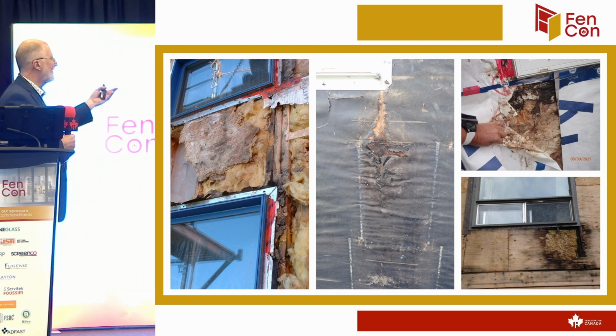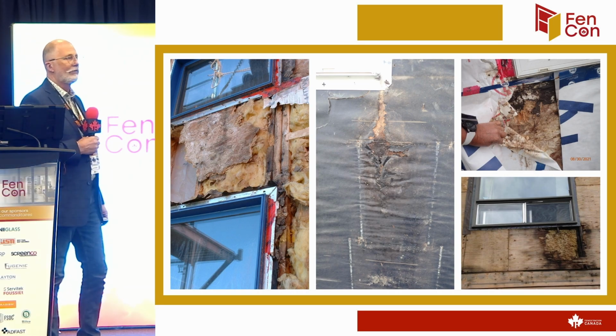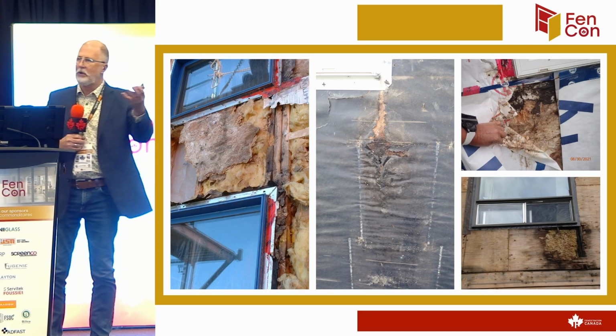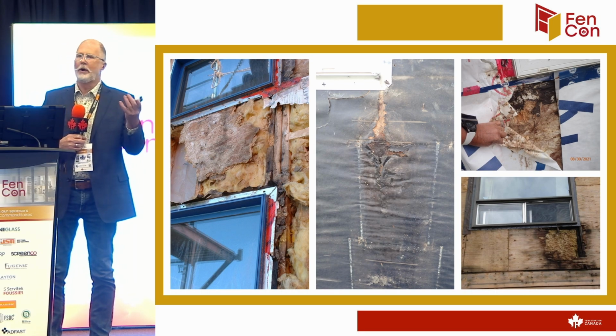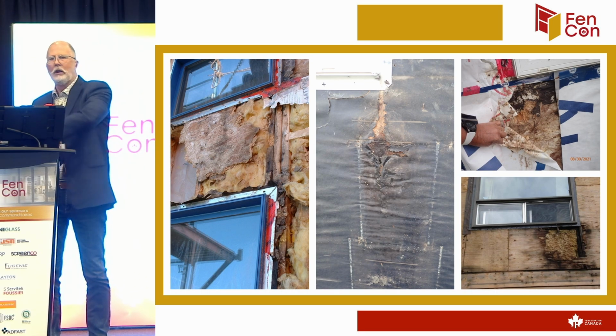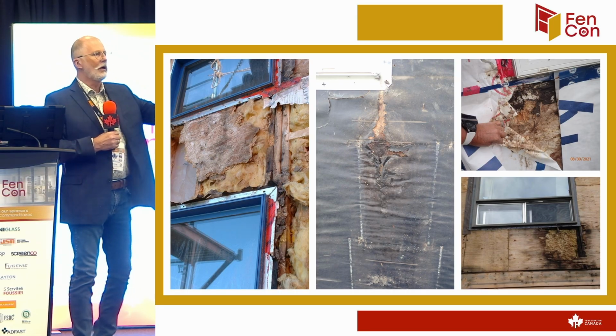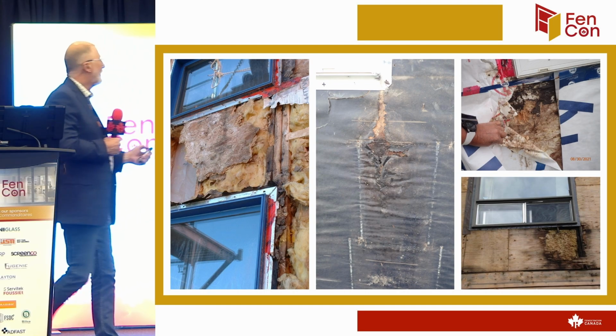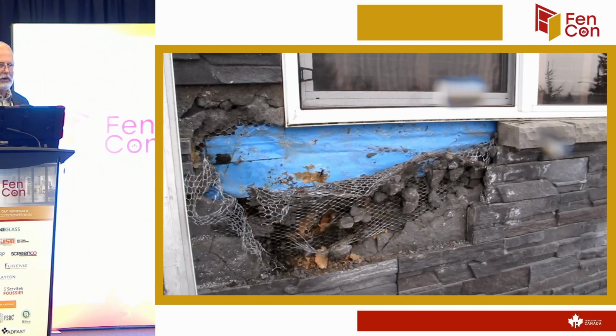So these are constantly things that we run into in wood frame construction because we haven't addressed the window. If we had the window properly protected and that water was directed out and over the house wrap, over the tar paper, how often would we see this kind of damage? We just wouldn't see it. So that's where a big part of our issues are.